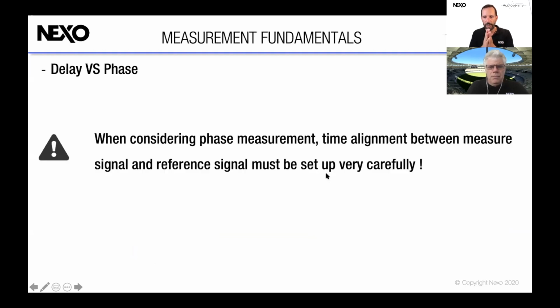So delay and phase, once again, this is very important for us. When you consider phase measurement, time alignment between the measured signal and the reference signal must be set very carefully. Okay, so you get the signal and you don't change it.